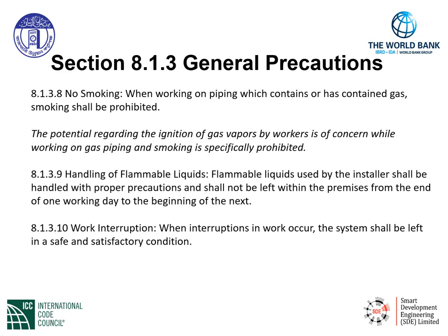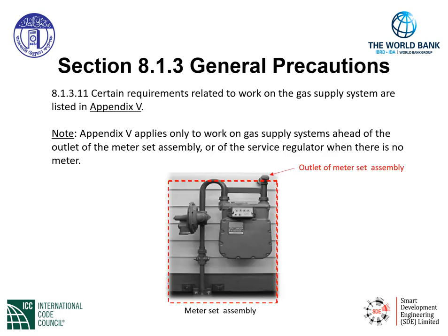If we're working on the piping systems, ladies and gentlemen, and we have to replace a faulty valve, we first begin with shutting down the gas piping system. Opening up the system, replacing perhaps a faulty valve, we need to make sure that the gas piping system has then been tested for any leaks and left in a safe and satisfactory condition. So, a good general precaution.